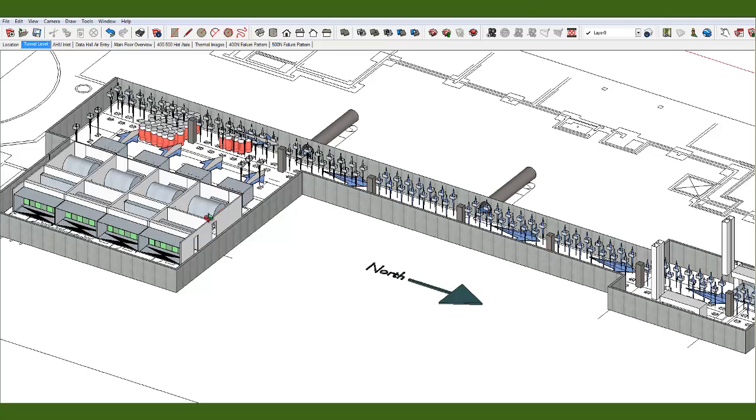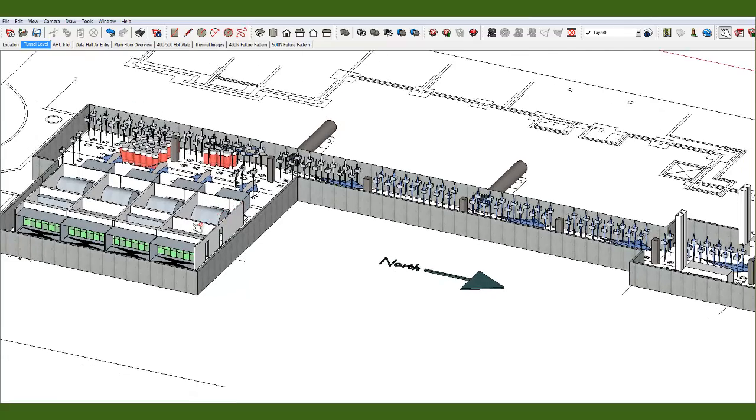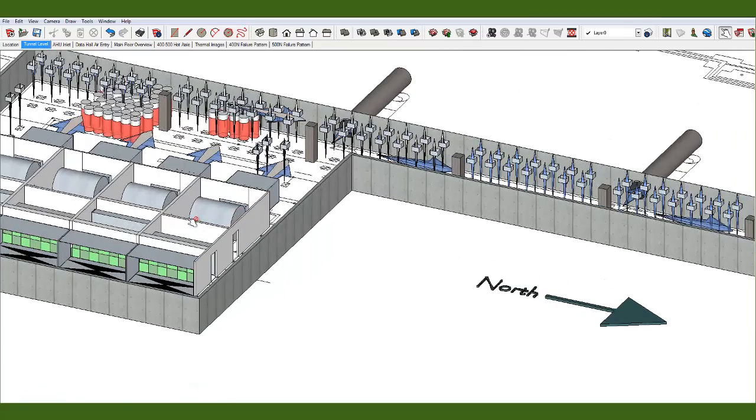Being an early free air design, it was designed by, at the time, really, office building architects, and not data center architects. And the filtration system, they were MERV 13, I believe. They needed to be at least 17, HEPA or better.